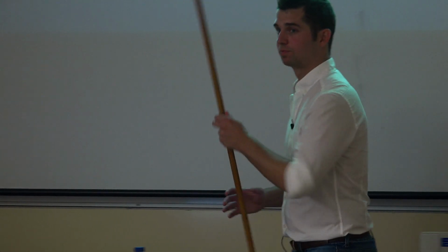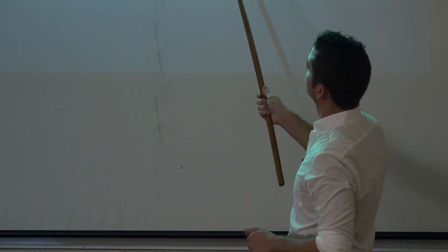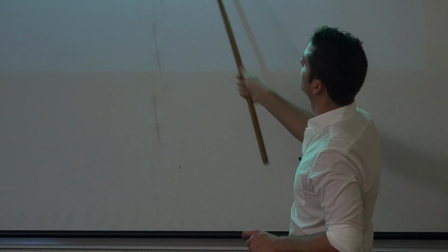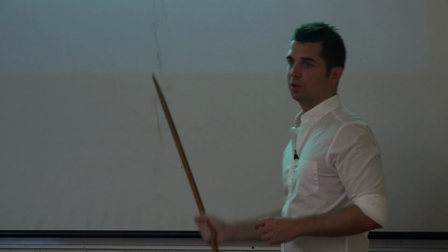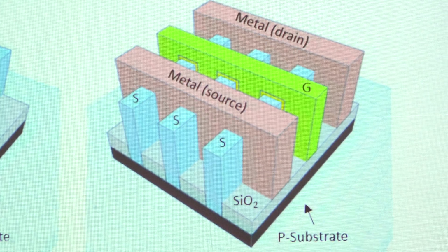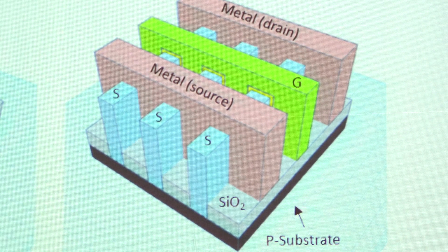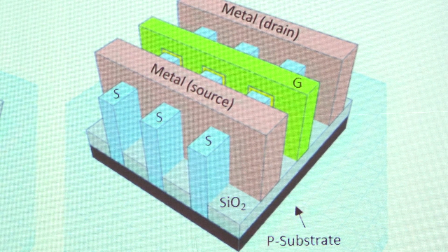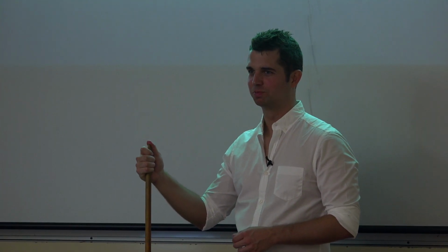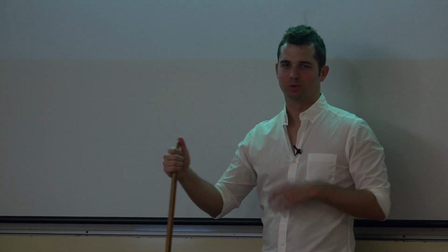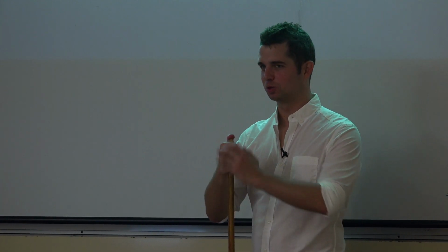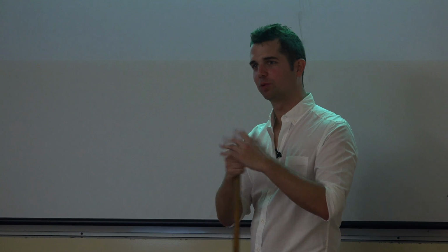For instance, here, what are the parasitics that you see here? You see parasitics from the source here to the gate, from this source to the other source, from the source to the gate, from this metal here to the gate. You have very complex parasitics here. When you go down to the other nodes, to the nanowires, you're going to have parasitics even more complex. But that's a problem for the process engineers, not for the design engineers, because we just receive the models and we try to do the best we can with the models we're given. I hope this answers your question.